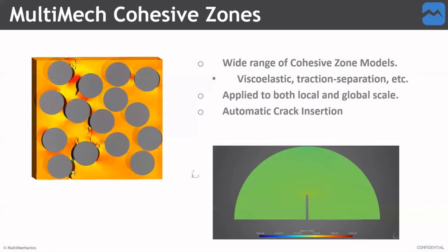You can make a microstructure that is anywhere from hundreds of nanometers to even millimeters, and as long as this microstructure represents the volume as a whole, you can use this. It doesn't necessarily matter how far you transfer between different length scales. So when we have displacements at the microstructure, we look at things more based on strain, which is a unitless number. And when we're looking at the global structure, it's up to the user to define the units.